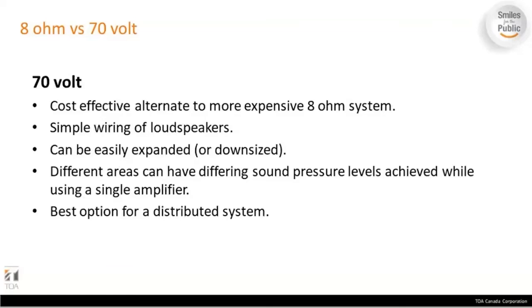So let's say you have a school which has 9 classrooms, right? How are you going to do series parallel in 9 classrooms? So what you do is you have 70 volt speakers in these 9 classrooms.